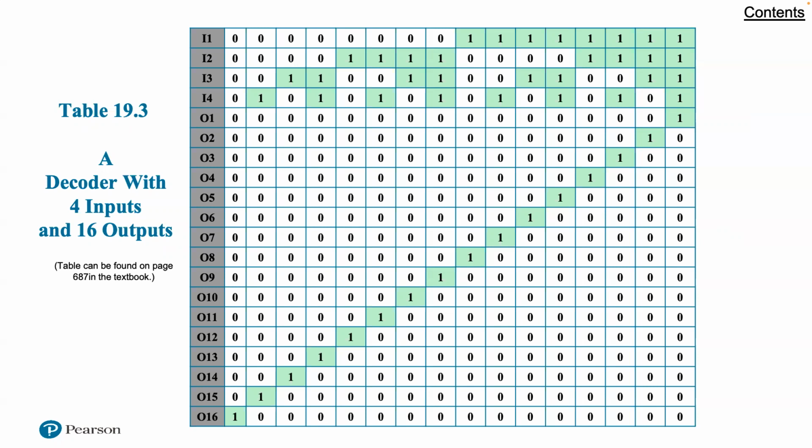First, consider the IR. The control unit makes use of the opcode and will perform different actions, issue a different combination of control signals, for different instructions. To simplify the control unit logic, there should be a unique logic input for each opcode. This function can be performed by a decoder, which takes an encoded input and produces a single output.